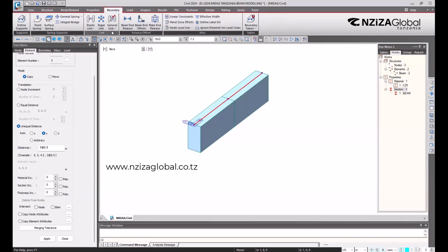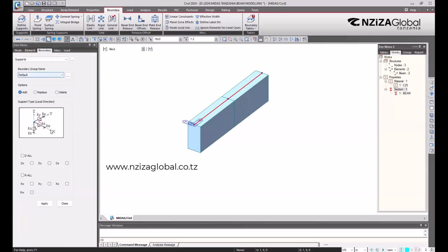For boundary conditions, our structures must be linked to the soil by the actions. Of course, they may be fixed supports, they may be free, or we can allow them to move a little bit. Like decks for roads, decks for bridges, they need certain movement, right? So we link them by using these elastic links. But when it comes to the interaction with soil, we need to provide the supports.